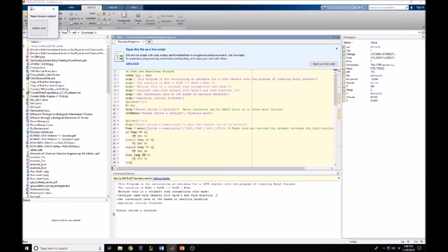Now, some of the other chemicals involved besides sulfuric acid, which is seen up here, are acetic acid, n-butanol, and n-butyl acetate. All of these are flammable and need to have a chemical powder for small fires and an alcohol foam system for larger fires. For small spills, you need to dilute it with water, then mop it up with the appropriate waste disposal. For larger spills, absorb using dry earth and non-combustible inert material. Then dispose of this according to the local, state, and federal regulations. All chemicals need to be stored and segregated in the approved area. Keep the containers in a cool, well-ventilated area and keep them tightly closed, sealed until ready for use. And you should avoid all possible sources of ignition.